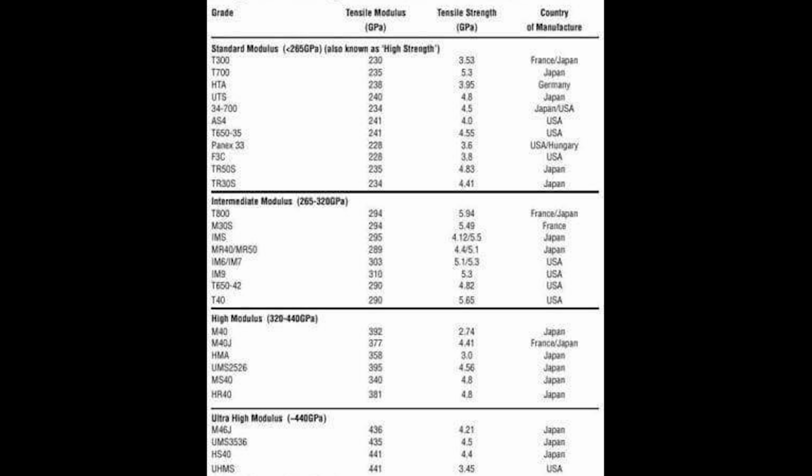You're getting fibers that are not straight, and they're really poor for handling compression. So you lose a lot of the compression strength. So this answers my other question, that if you make a carbon fiber sheet that's like 3 millimeters thick with all woven layers, that's actually worse. Yes, actually, it's better for shear, but it's worse for strength, and yeah, it will be very interesting.